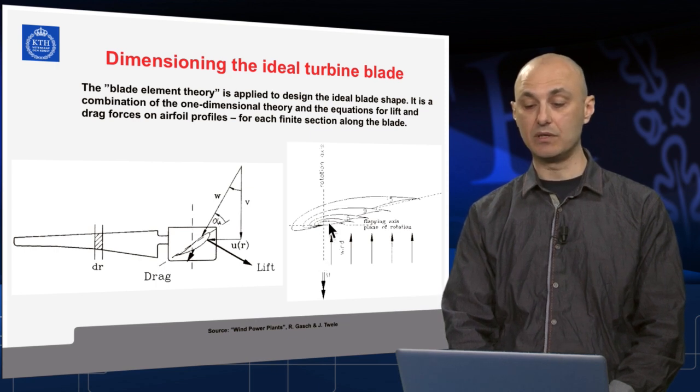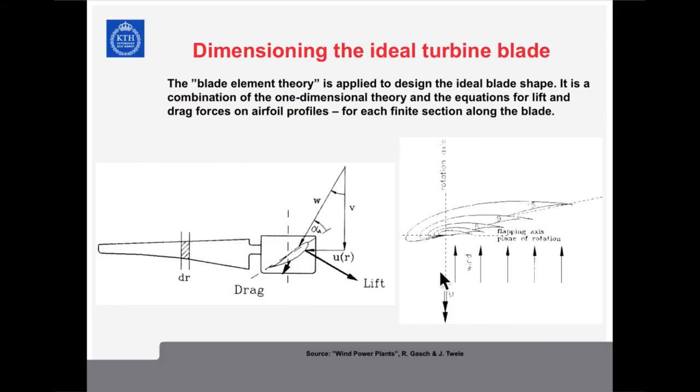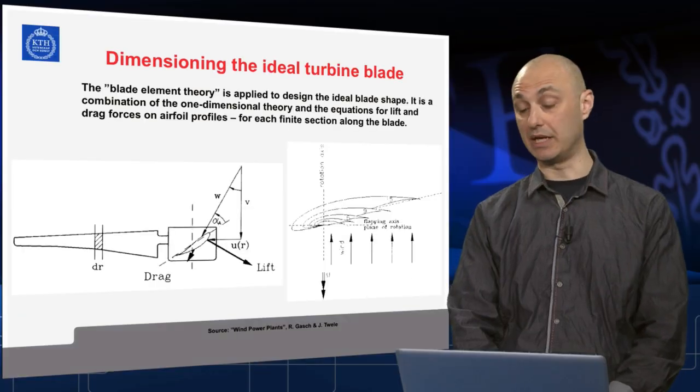And if we look from the top of the blade towards its root, we will see that it is built up of different profiles and it's twisted. The root of the blade is thick, solid, at high angle, while the tip of the blade is slender, a very, very streamlined profile, almost sitting along the axis of rotation at a close to zero angle of attack.